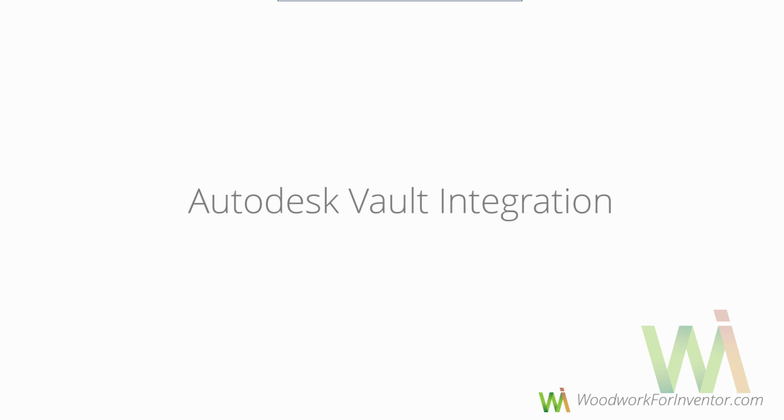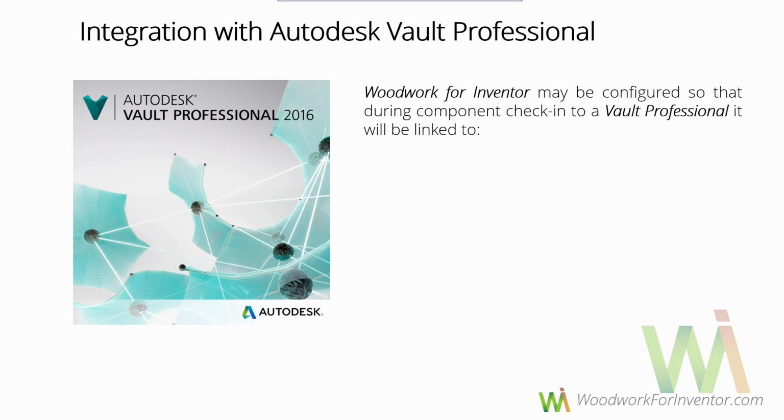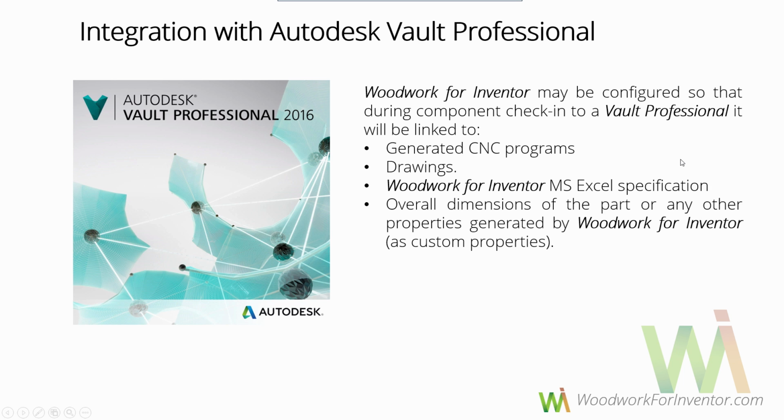Okay, so the next big question is the Autodesk Vault integration. We can configure Woodwork for Inventor in such a way that when we check a component into the vault, it automatically links the generated CNC programs as well as the drawings, the Microsoft Excel specification, and the overall dimensions of a part, or even each custom property which can be calculated by Woodwork for Inventor.